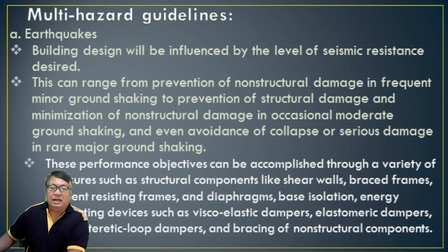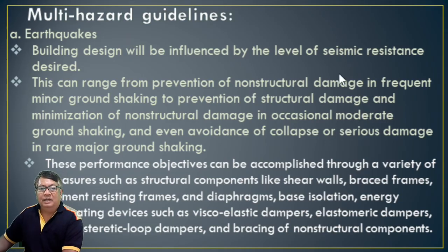So, multi-hazard guidelines. What are some of these multi-hazard guidelines? First, talking about earthquakes. Building design will be influenced by the level of seismic resistance desired. This can range from the prevention of non-structural damage in frequent minor ground shaking, to prevention of structural damage and minimizing of non-structural damage in occasional moderate ground shaking, and even avoidance of collapse or serious damage in rare major